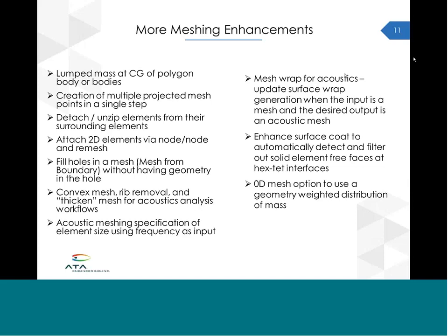There's a number of enhancements that are really related to acoustic analysis workflows, but they might be relevant to you even for more general meshing operations. There's a very handy way to create convex meshes. So if you have a body that you want to enclose with a convex surface, that's now a very easy operation. And if you are interested in acoustic meshing in particular, you can specify the element size using the frequency